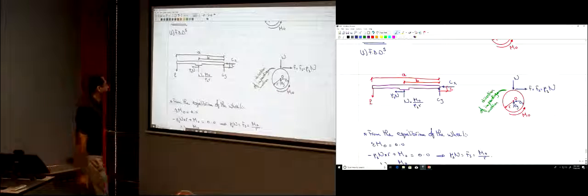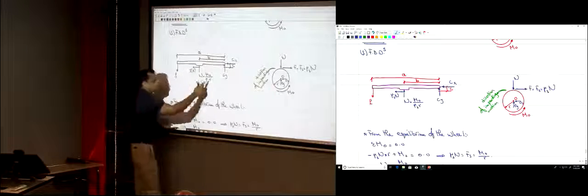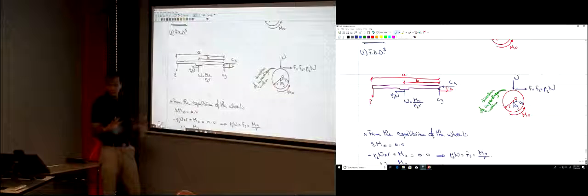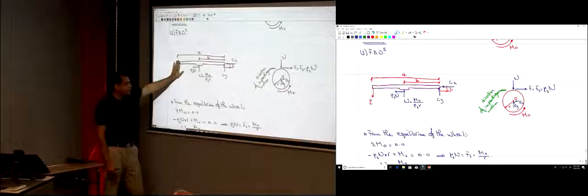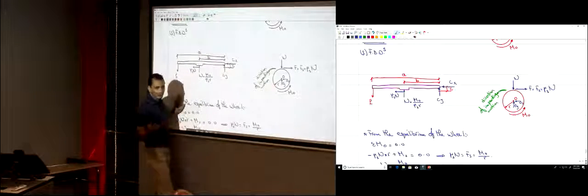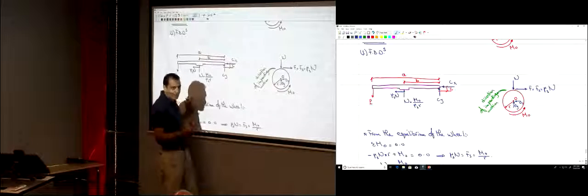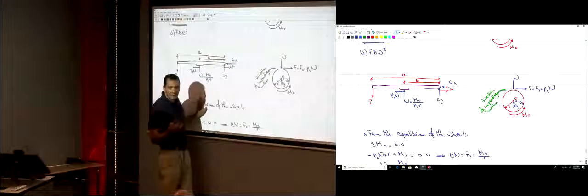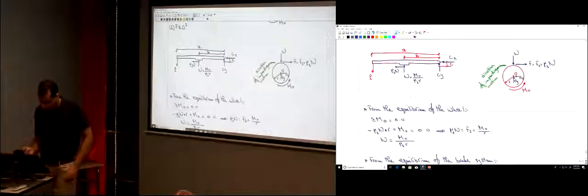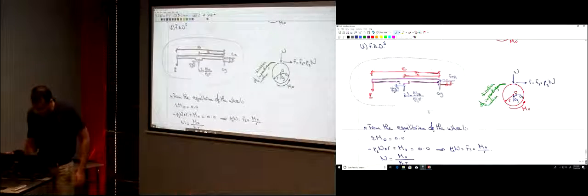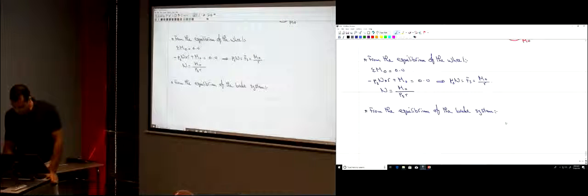I would like to find P. Now those are not unknown, right? I know them in terms of M naught, mu s, and r. I would like to find P. What are the other unknowns that I don't have here? Cx and Cy. I was not asked to find Cx and Cy. I want to eliminate them. So how to eliminate them? Take moment about point C. So let's take the summation of the moments about point C. Let's just copy this here so you have this available to you.